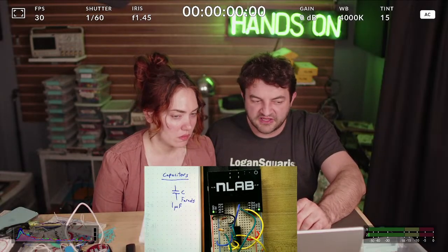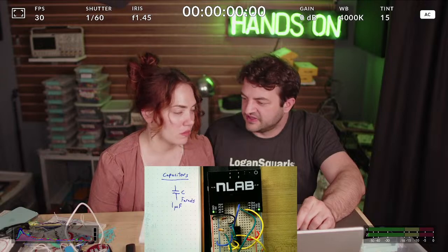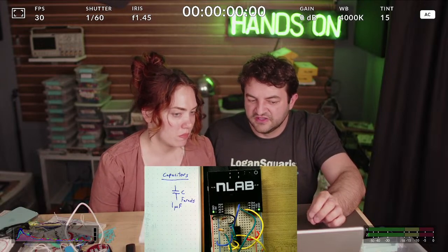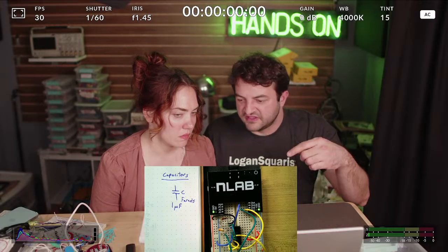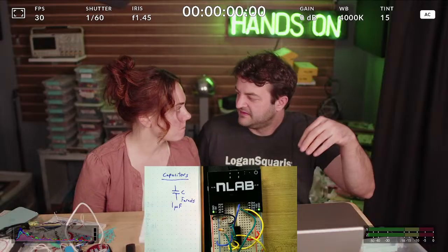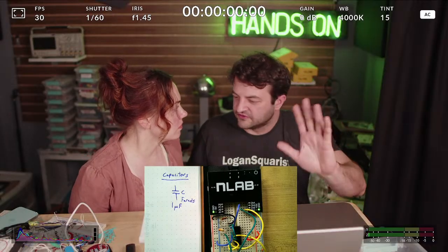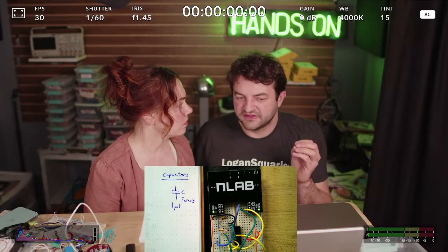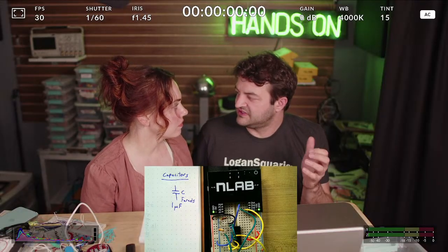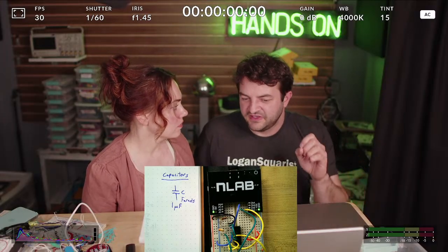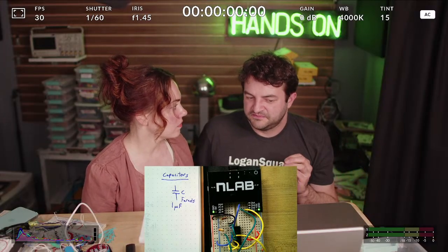And so you'd be like, I really wish I had 12 volts and I really wish that 12 volts could deliver 10 amps of current. So there'd be a circuit that would double and then double and then double the voltage from the battery to go from 1 volt up to 12 volts or whatever it needed. And then that capacitor would be capable of delivering that current, the energy stored in it, instantaneously. But it wouldn't have that much total power in it.